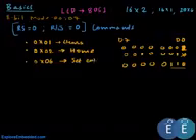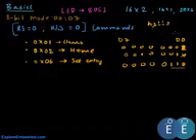Now what it does is, say we are displaying the string hello, it displays H on the first position and then it increments the cursor to the next position. So we do not have to do anything to increment the cursor after we display a letter. When we keep sending characters, it increments to the next position.